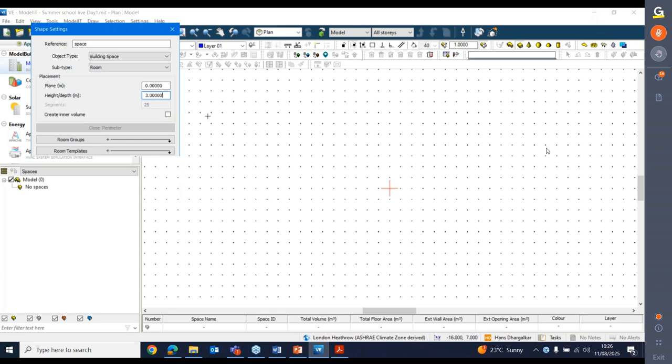So what we're going to do, we would trace the outline of the room to represent the inside of the external wall and halfway down the internal partition. You're going to get a single line model. Okay, so that's another tip there. So leave that switched off for thermal option, you can switch it on for daylight simulations if you've got a very thick wall. So we're going to show you later on in the session how we trace over a DXF drawing. Okay, so we're going to show that later on.